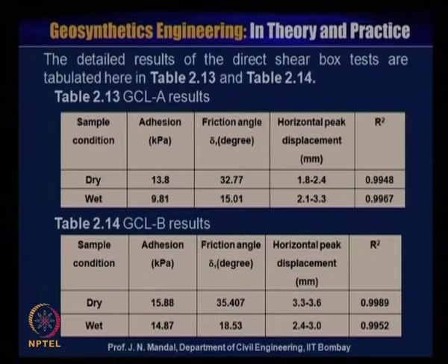Here the detailed results of the direct shear test are tabulated in this figure. You can see the sample condition, whether it is dry or wet, the adhesion value is 13.8, the friction angle delta is 32.77 for dry, and for wet condition 15.01. Horizontal displacement in dry condition is 1.8 to 2.4 millimeter, and wet condition 2.1 to 3.3 millimeter, and the R square is 0.9948 and 0.9967.